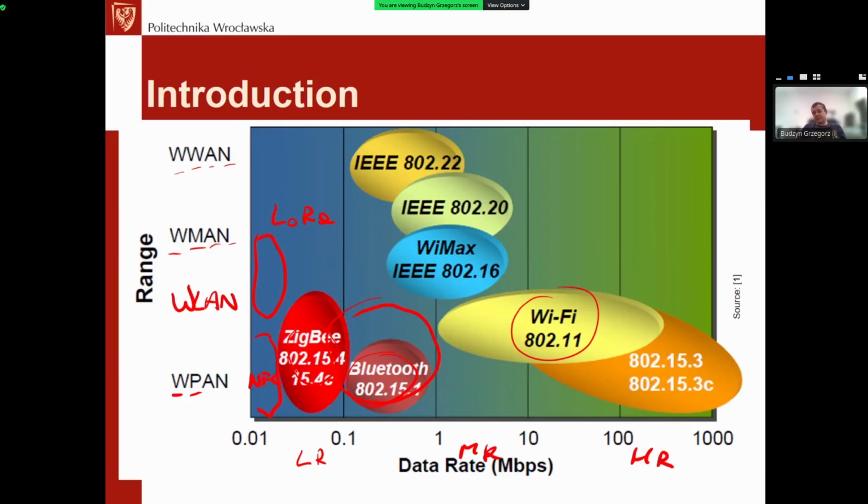So these are the free of charge options that we have today, working in non-licensed bands, because for example WiMAX, 802.16, requires licensed bands, and that's not popular in embedded systems. It's an access network. From the embedded systems point of view, LoRa, NFC, Zigbee, Bluetooth, Wi-Fi are the options that we are using today. And from the licensed band, LTE.